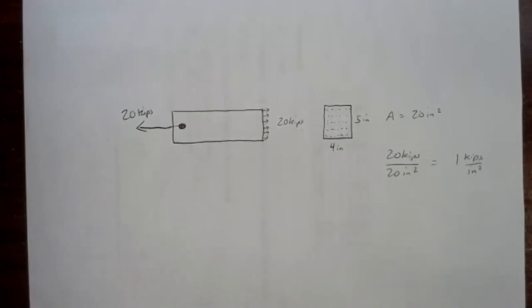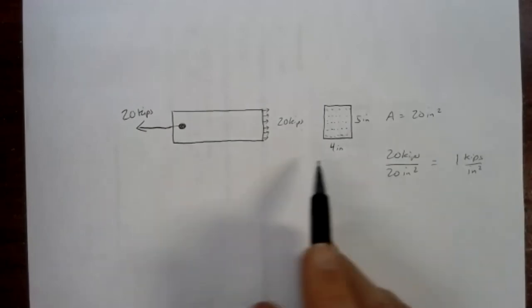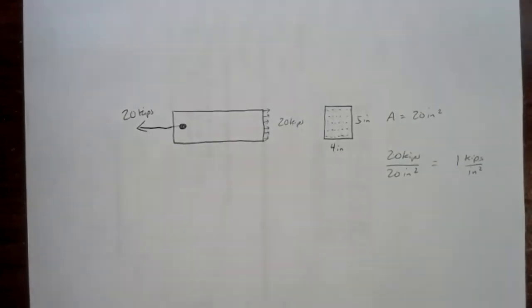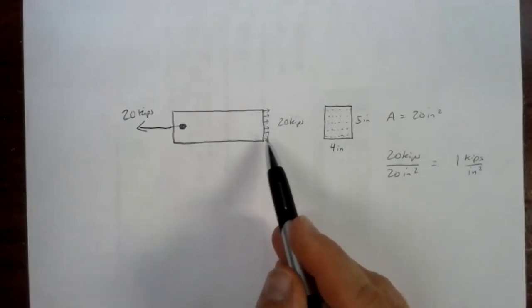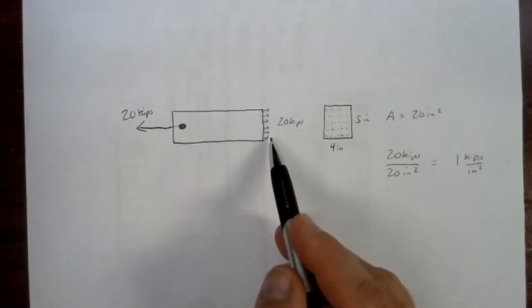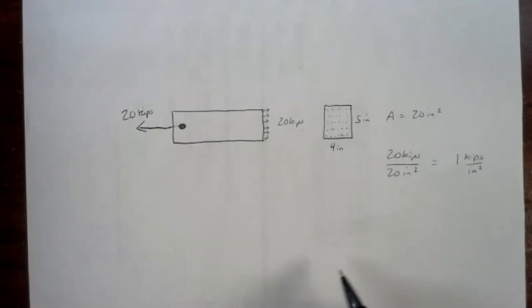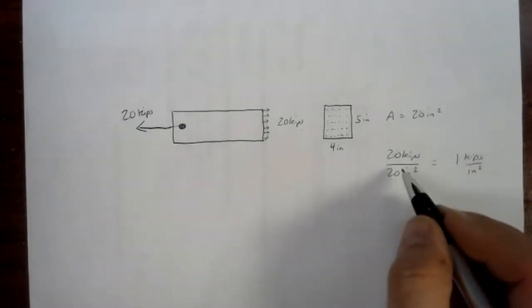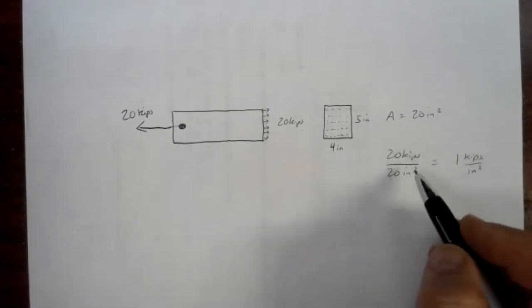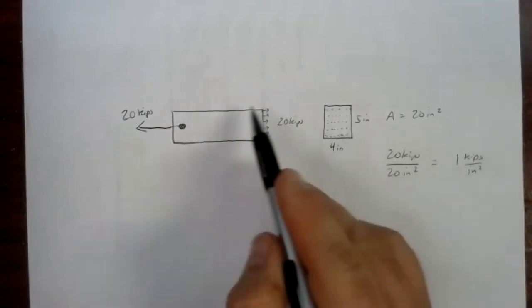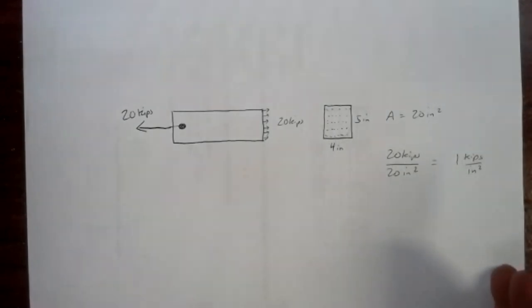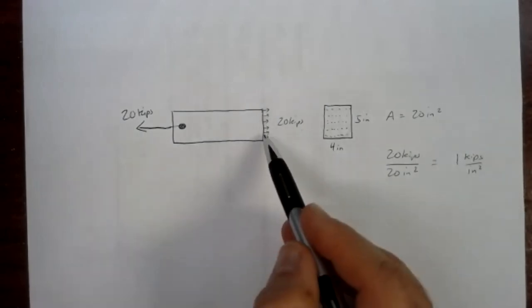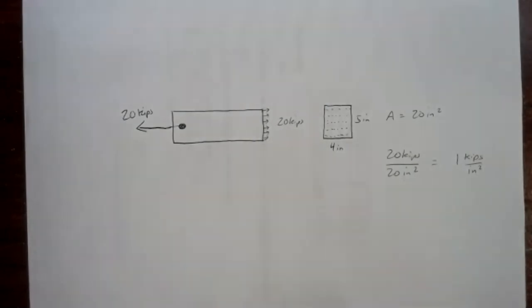It's an internal pressure. Now, we're used to thinking about pressures as forces pushing on a structure. A pressure could be a pull also. Pressures can be in tension or they can be in compression. Stress is really just another name for material pressure. It's how the forces that are applied externally to a piece of material are resolved internally. Stresses are how much force is on each square inch.